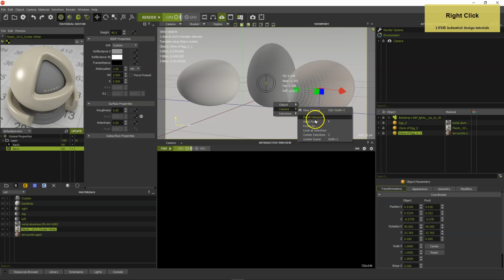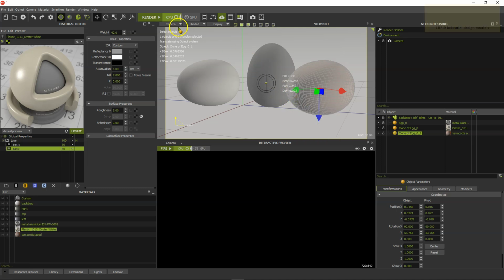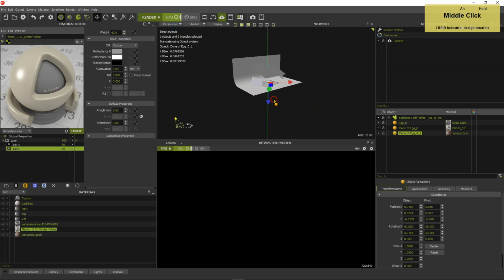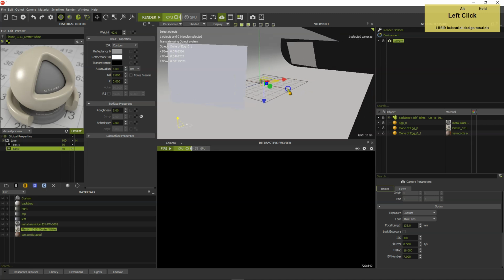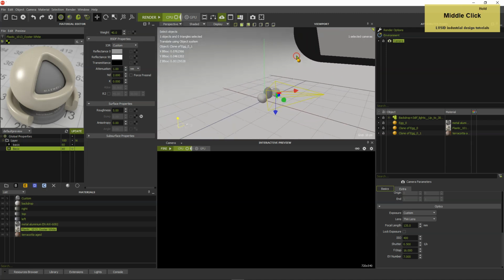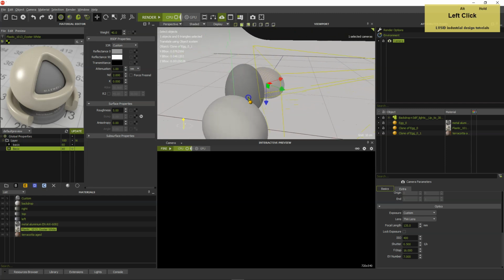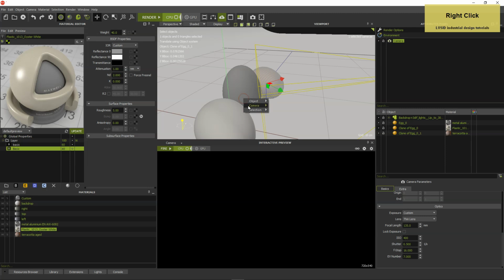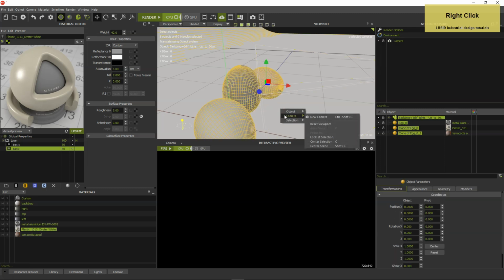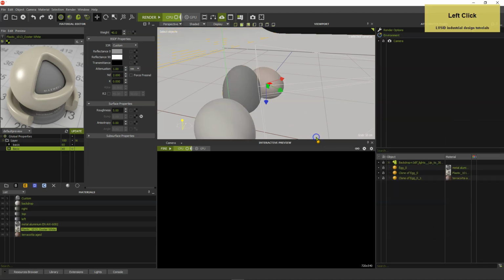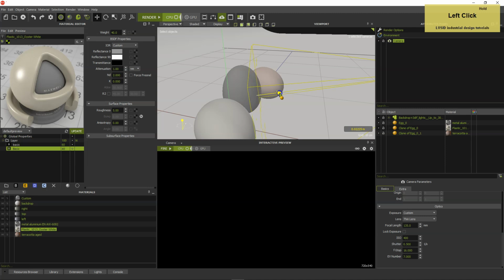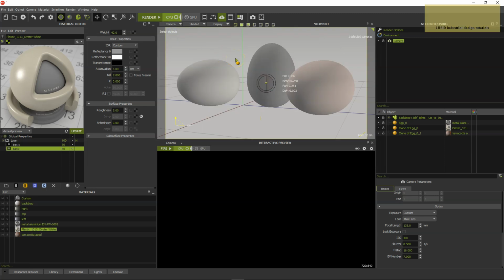Autofocus or set the camera's focal plane manually in the perspective viewport for more control. Change the camera's shutter to half a second because the HDR image we'll use for lighting is much brighter than the photo studio area lights.